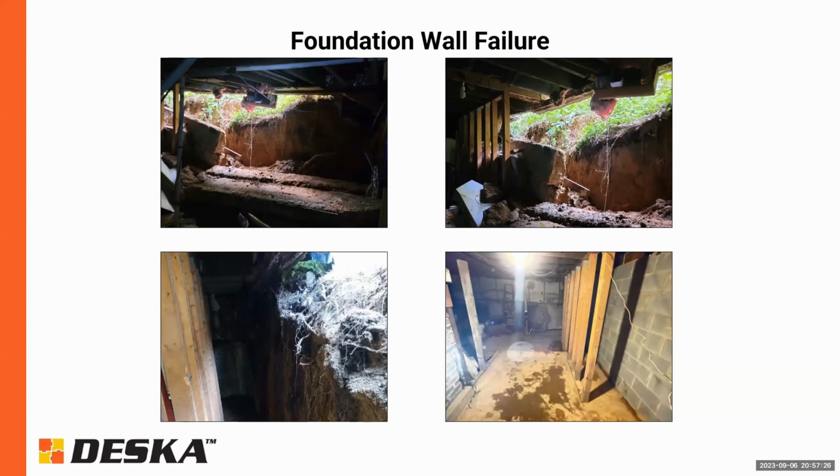In this particular case, we couldn't even get in there to properly evaluate it. Because it was so dangerous, we had to install temporary bracing first, then evaluate what was going on, and then design a wall replacement here. Which, if you look at the bottom right corner, you can see that's actually the new wall there.